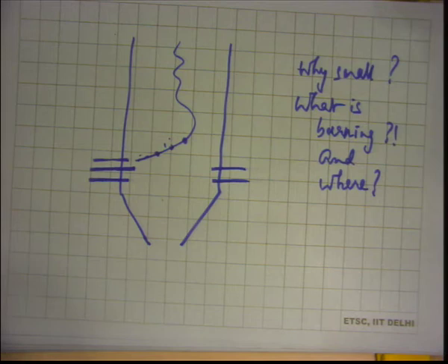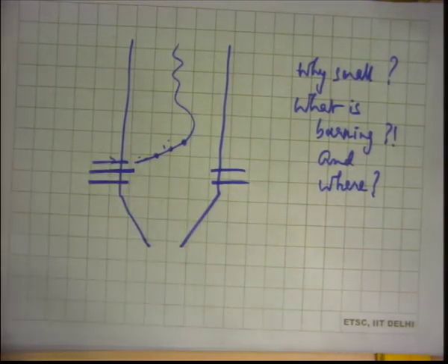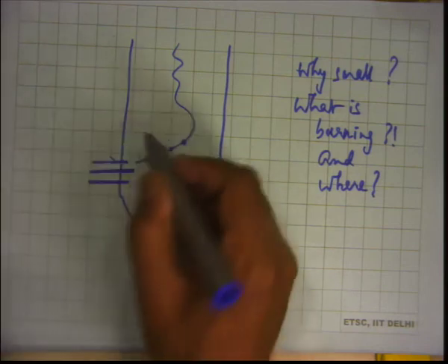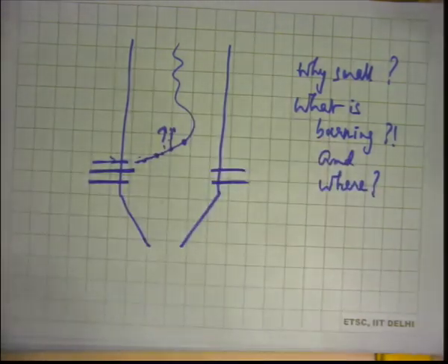It loses moisture. Primary air is typically preheated, so if it is heated to 75 degrees Celsius, it has lost some part of the moisture, but may not have lost all moisture, isn't it? When it is entering at 75, 80 degrees Celsius, it has lost some moisture, but we cannot rule out the possibility that it still has some more moisture.